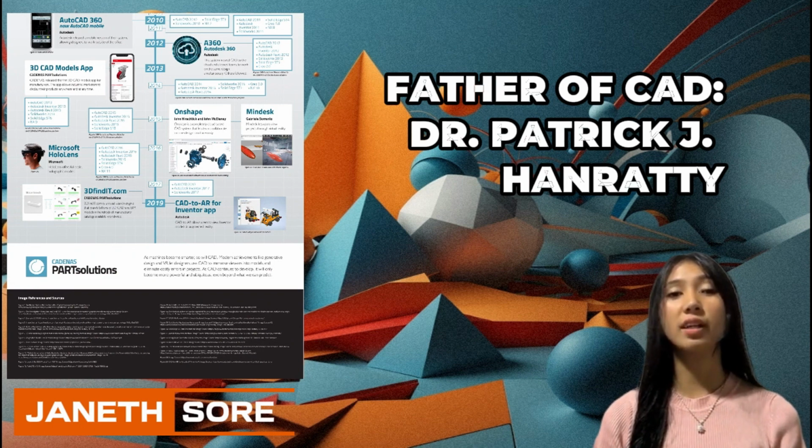So CAD really came into its own with the introduction of 3D solid modeling technology, which boosted the usage of CAE technology in industry. The development of 3D modeling schemes started with 3D wireframes. It was a major leap in computer geometric modeling as it allowed designers to use a single object and view it from multiple angles. However, wireframes are susceptible to ambiguity because the surface definition is not part of the 3D wireframe model.